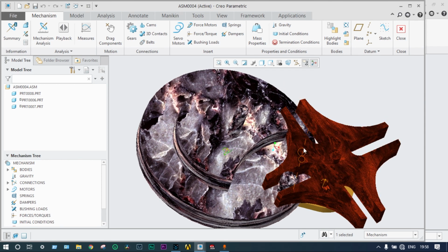We can do some other things also, like curve tracing, but in this case curve tracing will not have any kind of meaning, because we know how the different parts are moving. This is already having one circular motion. This is also a little bit of circular motion. That means here continuous circular motion is converted to intermittent motion, right? So here it is actually meaningless to find out the curve tracing. We can do that one also.